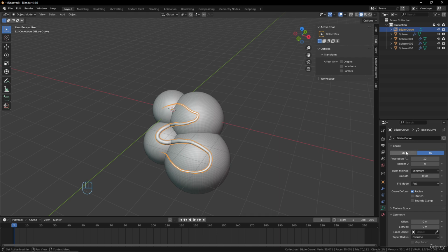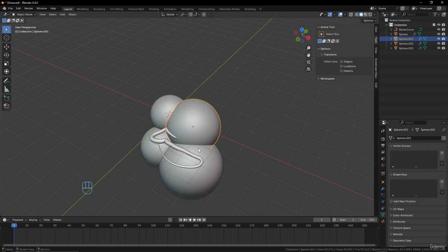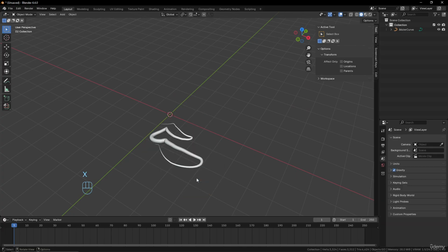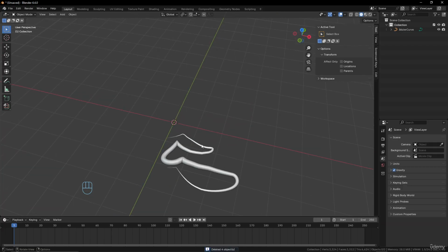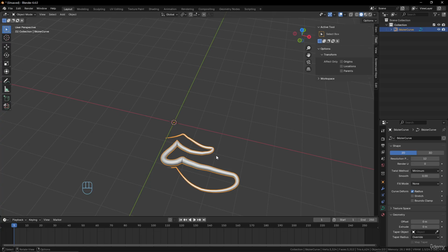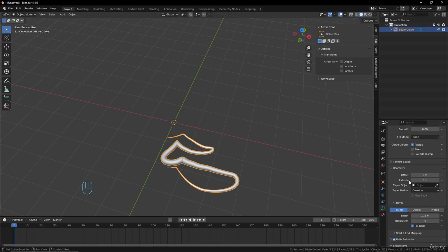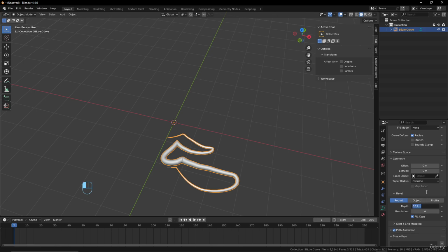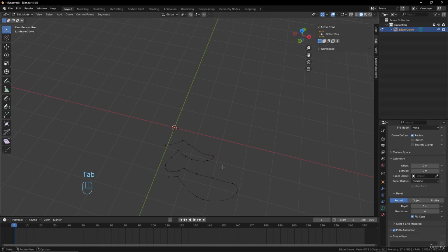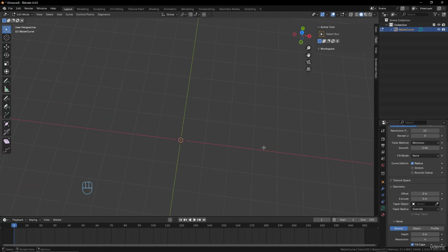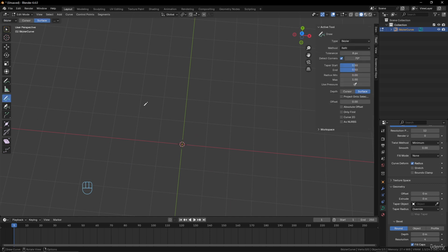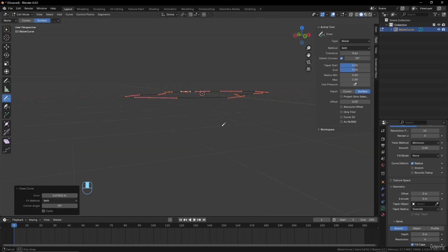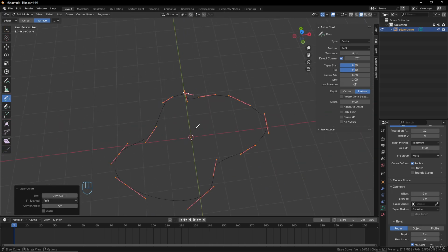So the 2D possibility here will make a shape that sticks into the Z axis. So like that, it will be always on the floor, let's say. And with the 2D shape, you can use other methods to draw things. Like for example, if I use 0 here and come back, I will remove all the vertices. So now everything I will draw, for example, if I draw a shape, everything that I will draw will stick into the 2D space here, into the Z axis.